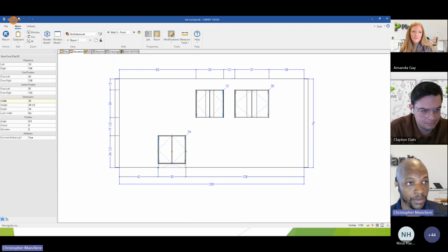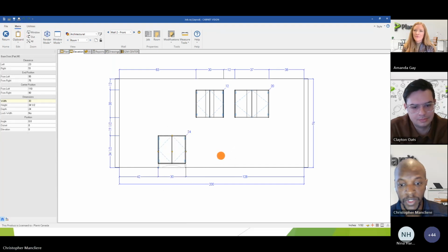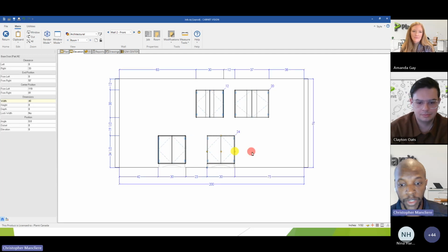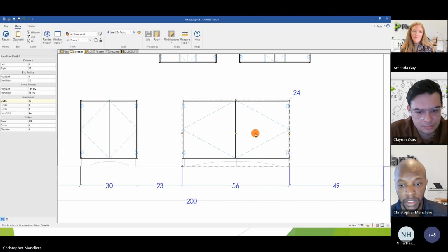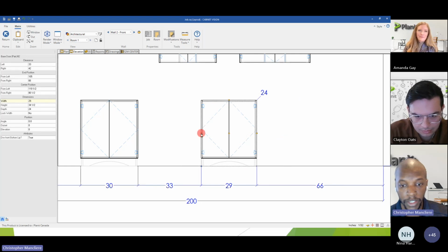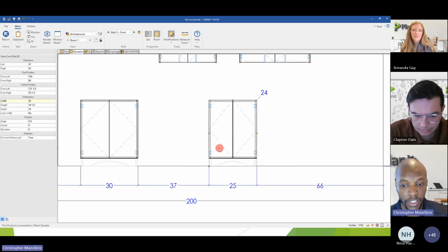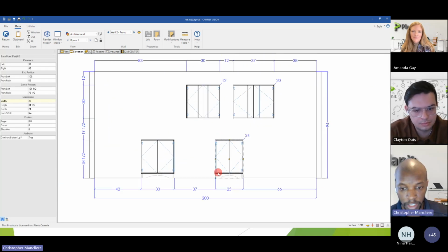So I will save the job, copy the cabinet, and change the width, and make sure that I keep my 2.5 on my part. And I can change the width, make it wider, shrink it, and this is still the same height because this is constrained now in my toe kick.